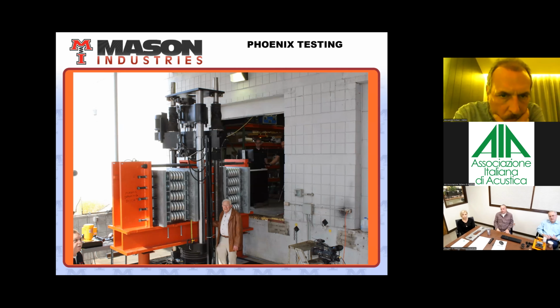We do a lot of testing. The founder of the company is in the photograph, Norman Mason. We were bidding a project in China, in Hong Kong, and it was called the Lyric Theater. And we built and designed the spring required for the project. And then we did horizontal testing because there was high wind loadings due to typhoons, and they wanted to know what the spring constant were and how the building was going to react under the load of high wind. And we established that by doing some independent testing.